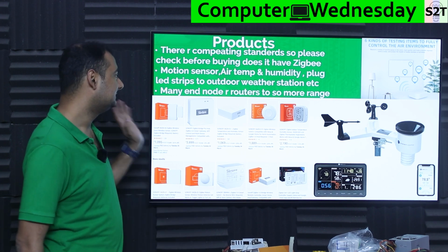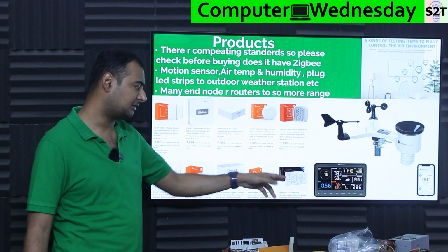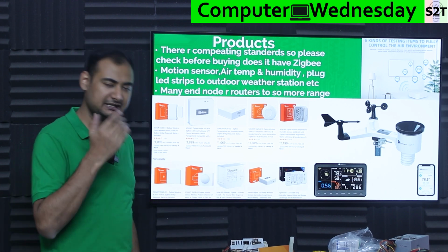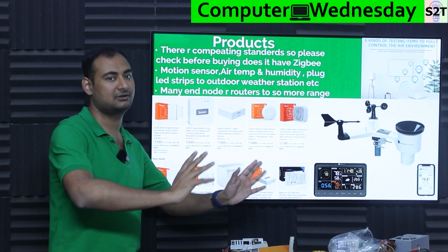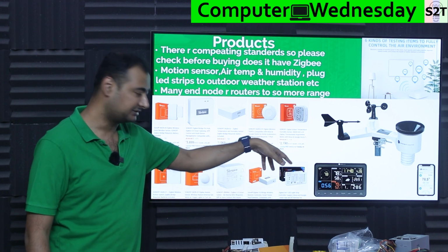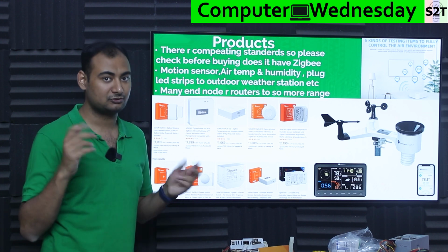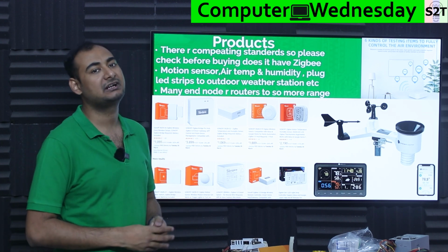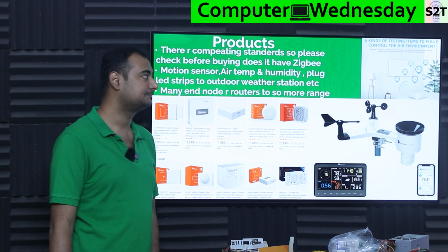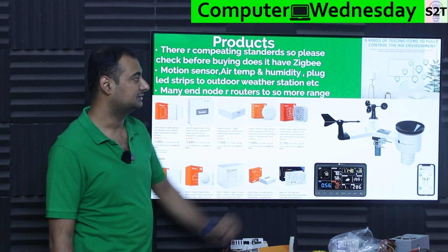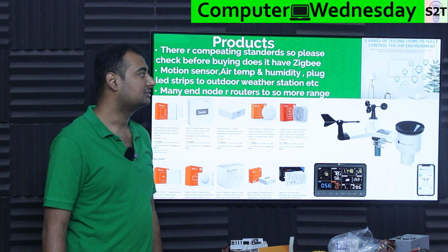So that's desirable. And be mindful, many big, powerful nodes, if you read the manuals, many will say it can act as a router also, meaning you don't have to do anything. It's just like, yeah, I'm an endpoint and a router, so it will be there. If it can receive a signal from someone else, it will allow it to hop. So you can have a lot of devices that, from your point of view, are just end devices, but you no longer have to spend money on routers. Sometimes it's required, sometimes it's not, but be mindful of that. So a lot of products are available. You have CO2 monitors, humidity monitors, temperature monitors, pH monitors, a lot of things.